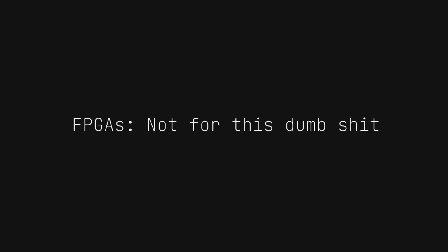I remember that when I tried writing a fully parallel 3 by 3 I64 matrix multiplication, the synthesizer requested 1 million nodes. My chip only had 25K. It seems like FPGAs are meant mostly to work as I/O support for microcontrollers or other embedded systems by dealing with communication protocols, signal generation, buffering, bit banging, and stuff like that. Operations like ray tracing, geometry collision, or graphics processing require a lot of higher-level operations, like floating point division. FPGAs are out of the question for these. It didn't work, so I just gave it up.